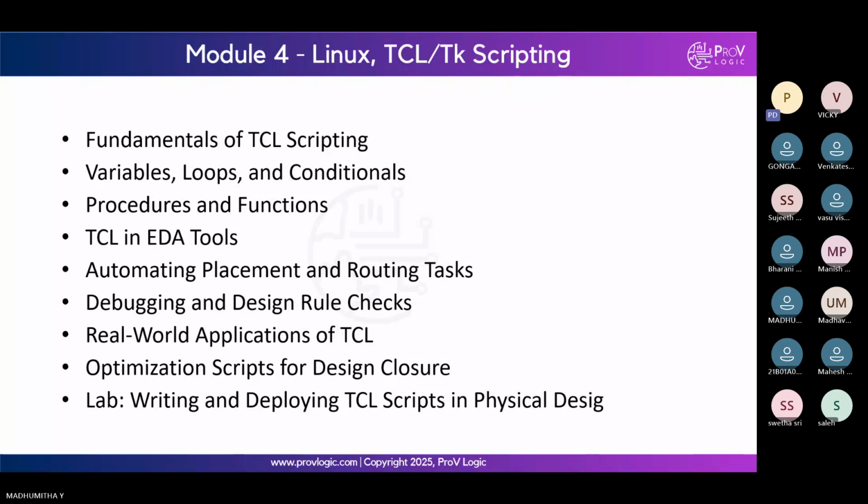Activity information will be present in the SAIF file. If you take a clock cell, the clock will be very actively switching because it generates clock signals continuously. So it is a continuously switching cell compared to logic gates or buffers. The activity value for the clock will be more compared to logic gates and other buffers, inverters or sequential cells.